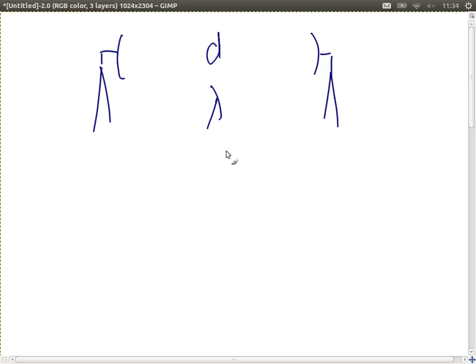The free space loss model tells us the relationship between these factors, and if we start, we transmit a signal with some power level, PT. If our transmit antenna has some gain, GT, our signal comes out of the transmit antenna. We start with PT. The transmit antenna introduces some gain, increases the signal.